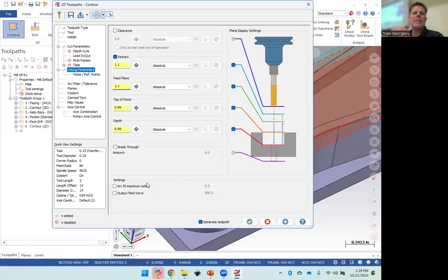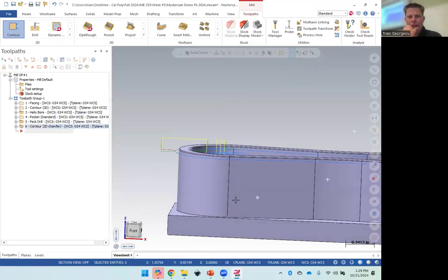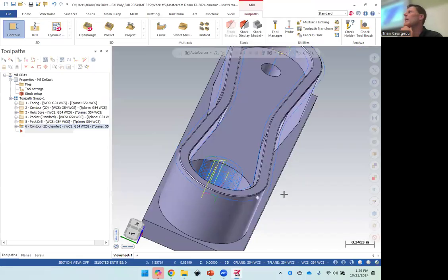So if I give it the same depth of the top of the part, it uses the trig and the tool to figure out the right size with that box. So when I hit check mark, everybody see it rounded the tool around the outside and the inside of my part right there with some lead in and lead outs.